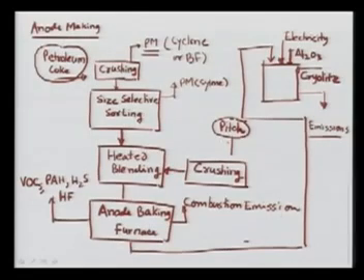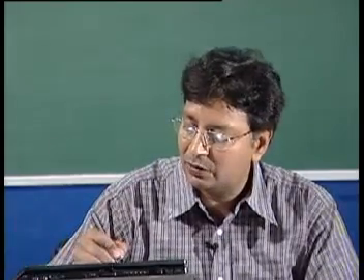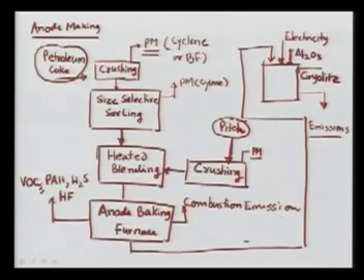But before the pitch can be used, it is processed through a crushing operation, as you can see here. And again, the moment you see crushing, there is a lot of particulate matter emission. After the crushing is done, it is mixed or blended with the petroleum coke, which is already in fine particulate form, and then you supply some heat here, because both are made viscous, and we get the heated blending here.